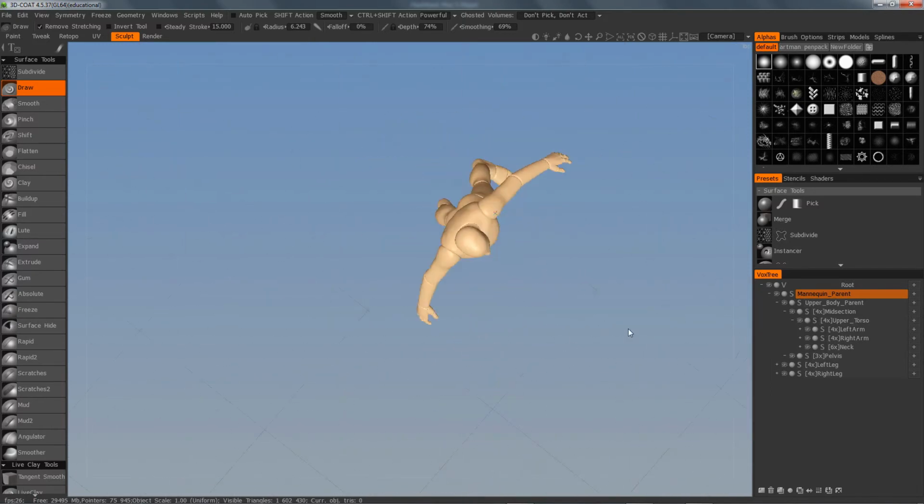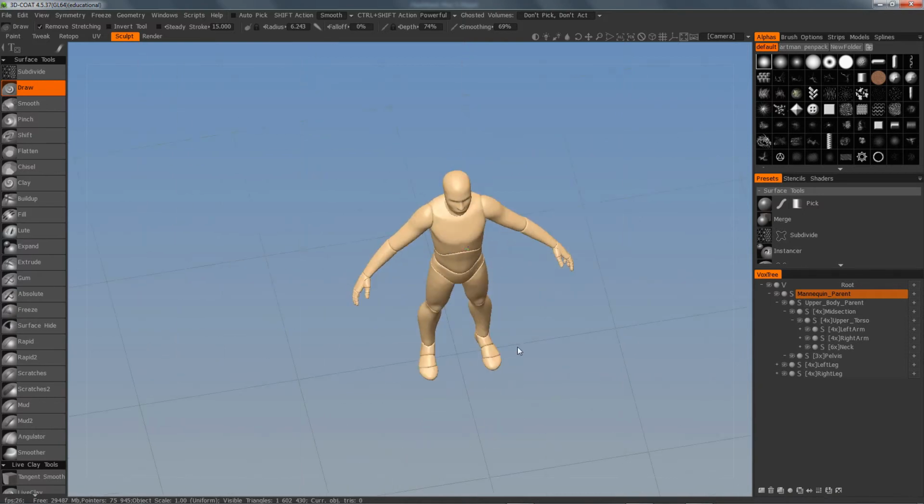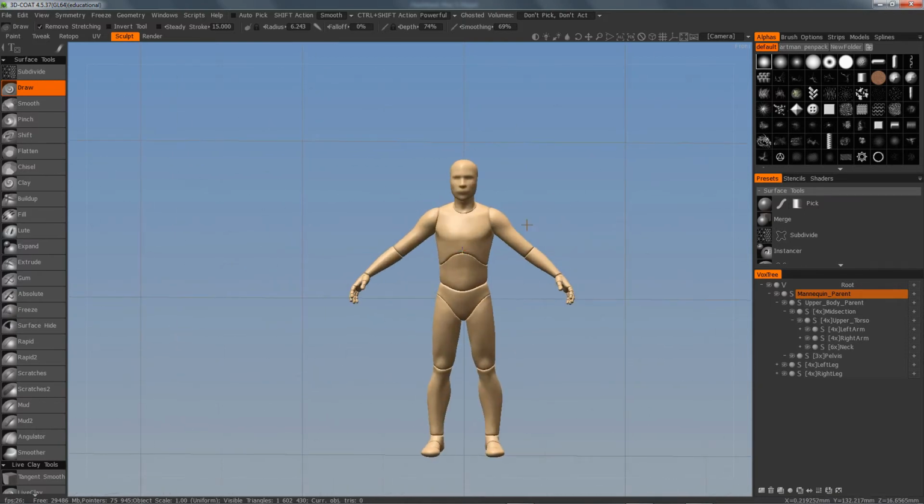And it feels very much like Rhino. If I'm over the model, in order to get it to do the same thing, I have to hold down the Alt key. That icon you see right there, the circle with the red mountain in the middle of it, the red bell curve, that's a brush. So if you see that and you touch down, you're going to start sculpting on something. So Alt acts like a clutch that actually disengages the brush from the surface and allows you to use it for navigation purposes. Okay. So that's revolve. Left mouse click outside the model, Alt left mouse click on the model. Pan is middle mouse button.